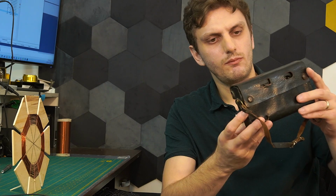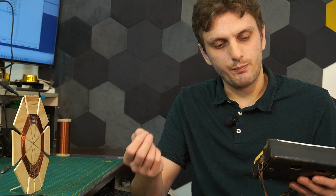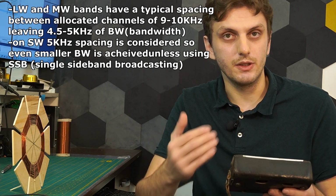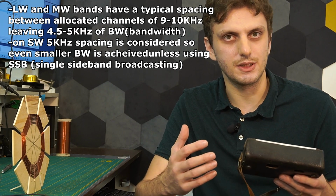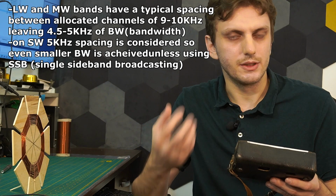Now, it's not the cleanest sound, and there's two reasons for that. On the one side, the amplitude modulator isn't perfect, so you can make far better amplitude modulator schematics than this thing. And on the other hand, in most AM radios, because of the way in which the frequency bands are allocated, you can get a maximum of 5 kHz of bandwidth. So you can definitely not hear the high frequency sounds that are around in most songs. So that's why AM radios sound a bit poorer in sound quality.